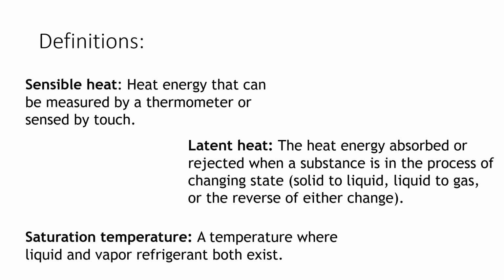The saturation temperature is a temperature where liquid and vapor refrigerant both exist. That saturation temperature was exactly what I was showing you on the pressure temperature chart. So if it was 40 degrees and it said 76.1 psi, that is your saturation temperature of the refrigerant. That's where it's changing states, right? And it could be a mixture of both at the saturation temperature, okay?